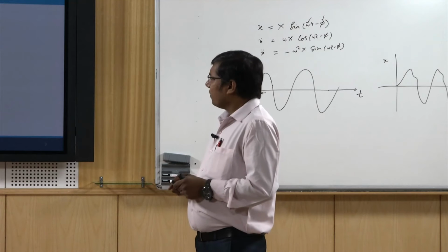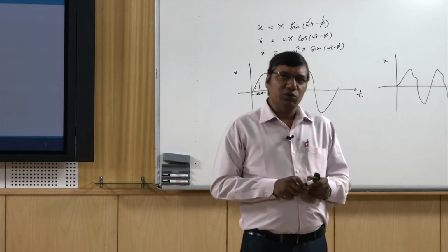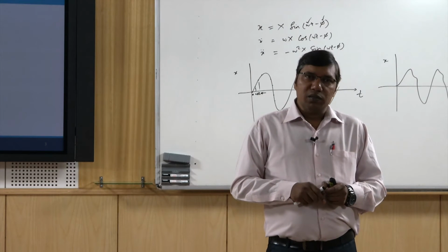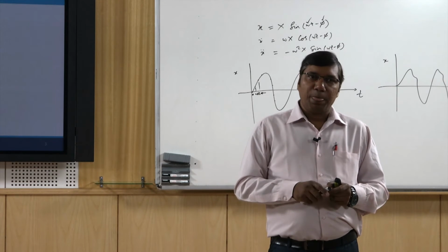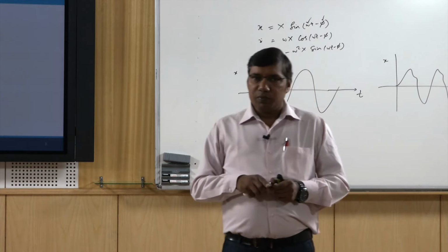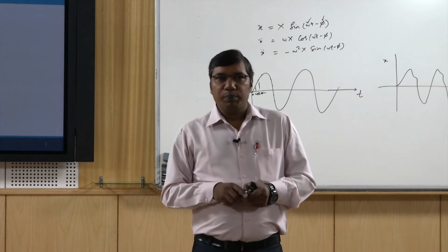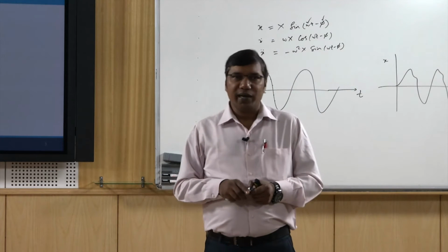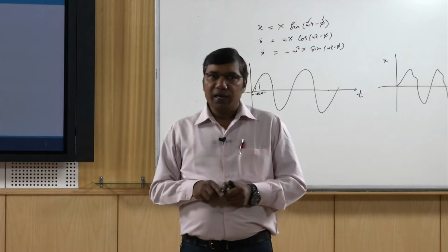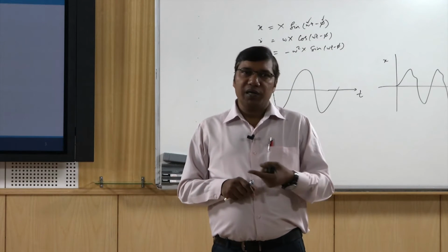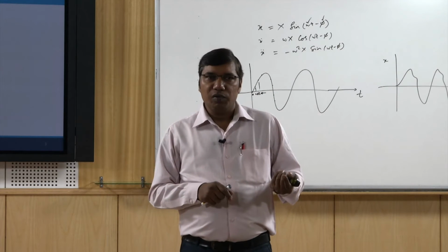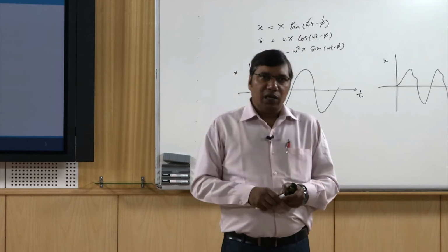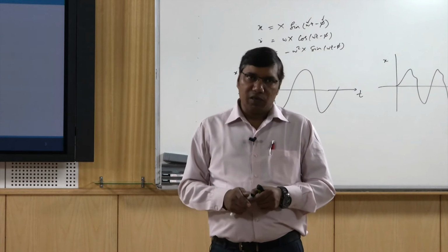Then electrodynamic transducers. These transducers use the characteristic of the inductor, because the voltage in an inductor is proportional to the rate of change of the current. They use the principle of electromagnetism, and we can relate the rate of change to the velocity, because velocity is also the rate of change of displacement, and we can relate it to find the change in the voltage of that inductor.